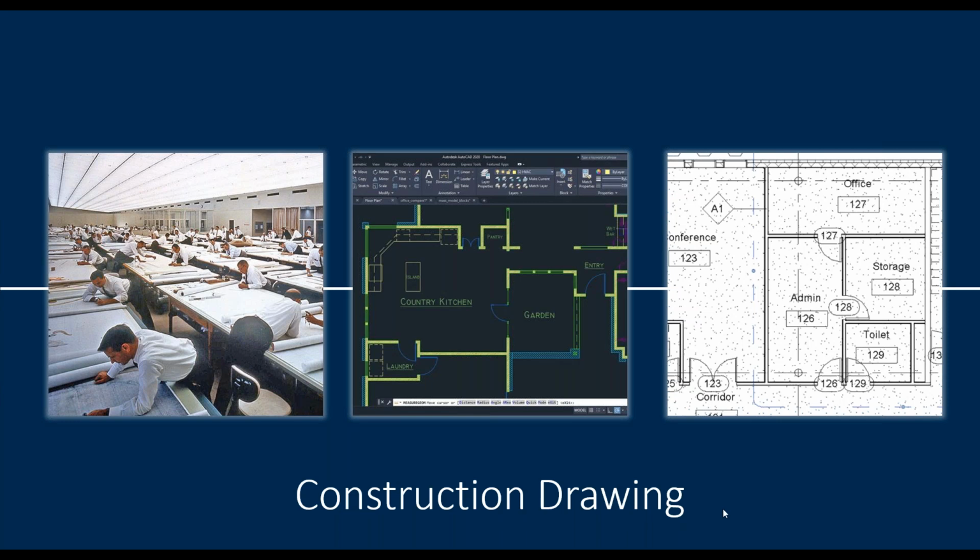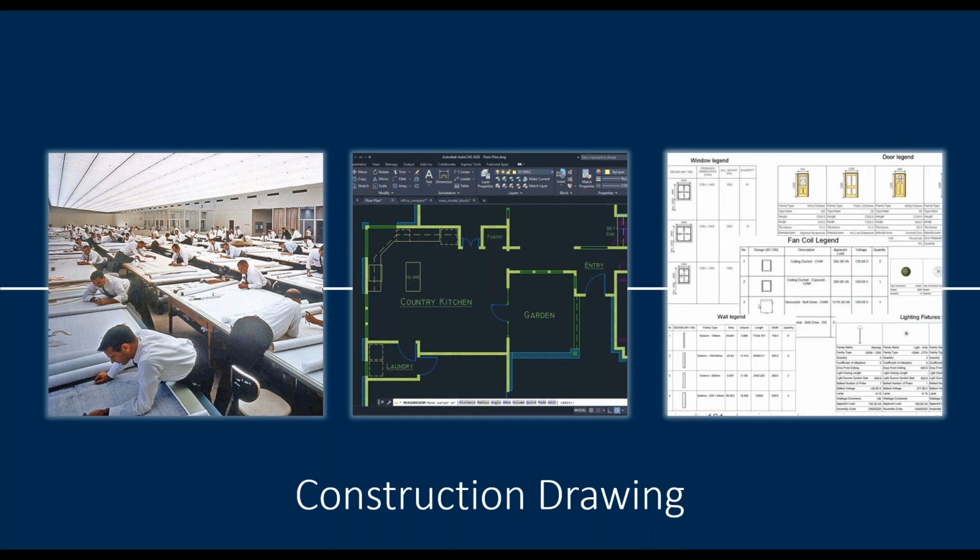And then, of course, when you move over to 3D tools like Revit, you will produce your drawings in a very similar way in terms of the way that it looks in 2D. But what is the addition to this is that with Revit, you've also got tools for scheduling in the same place, right? And so it's not only one type of element that you can schedule, but you can schedule almost any element that you've got in your Revit model. And so that is when we talk about BIM. So we're not just producing a 2D drawing, we're producing information that relates to the geometry on the drawing. And so that's where we would like to head, because now you're actually getting value out of the information.